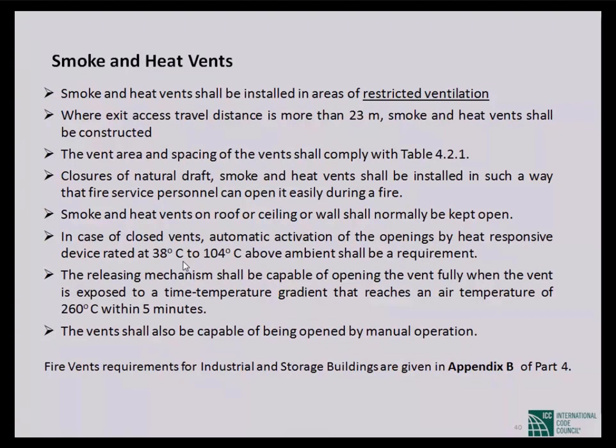Closures of natural draft smoke and heat vents shall be installed in such a way that fire service personnel can open them easily during a fire. Smoke and heat vents on roof, ceiling or wall shall normally be kept open. So you have to think that way, that this will be open.